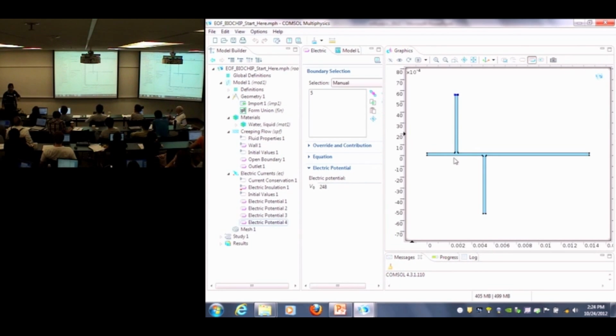And then this electric field will move the fluids. So now what we have is two physics, but there is no coupling of the physics. There is no stitching point. How are you going to couple it? I can solve the electric current separately, and I can solve the creeping flow separately. Nothing will basically affect anything. But we need to ask how the coupling comes into this model, how there is an electroosmotic effect.